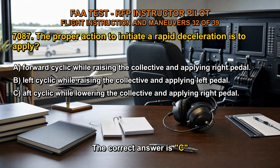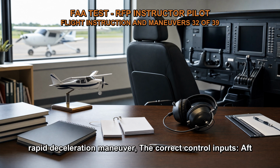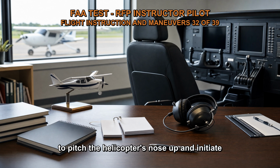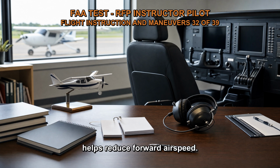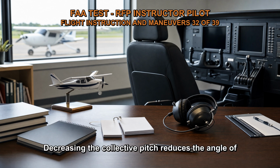The correct answer is C. When considering the proper action to initiate a rapid deceleration maneuver, the correct control inputs: aft cyclic. The pilot should apply aft cyclic input to pitch the helicopter's nose up and initiate the deceleration. By pulling back on the cyclic, the pilot increases the pitch attitude of the helicopter, which helps reduce forward airspeed. Lowering the collective: the pilot should simultaneously lower the collective pitch.